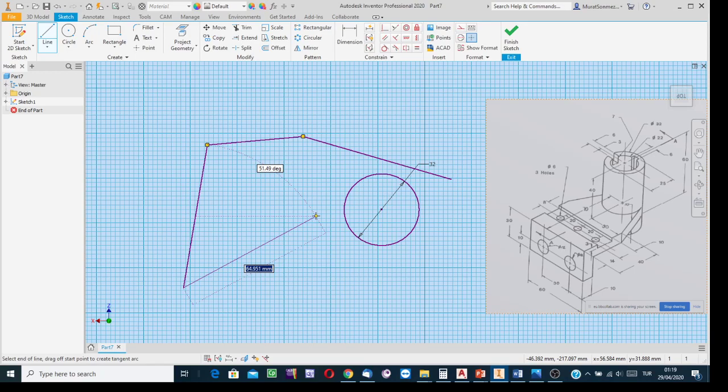Well, that point will be in alignment with the midpoint of the already created feature, this one. So when I attempt to change the location of the terminal point via inputting a constraint, I receive a message. Inventor will say that no, it cannot input such a constraint because that point is not free to take any constraint. It is already positioned with respect to the midpoint.